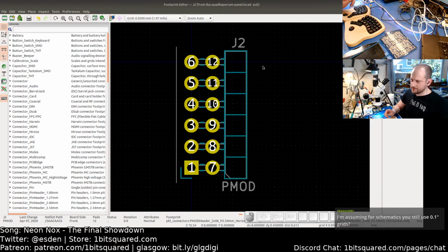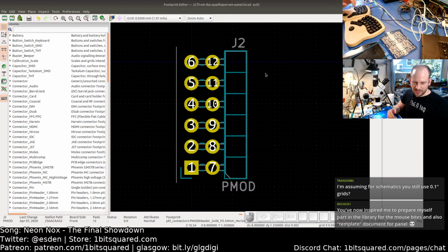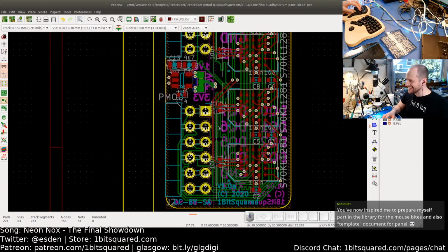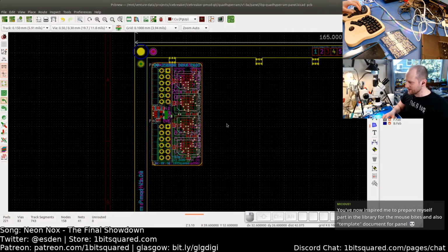The industry for the PCBs, at least from the mechanical standpoint and talking to the PCB manufacturers, they all just switched to metric by now. They can handle your Imperial designs, but they are basically converted to metric anyways. So all the modern PCB or Gerber management tools are pretty much all metric. I'm glad. I hope that's a useful recommendation there.